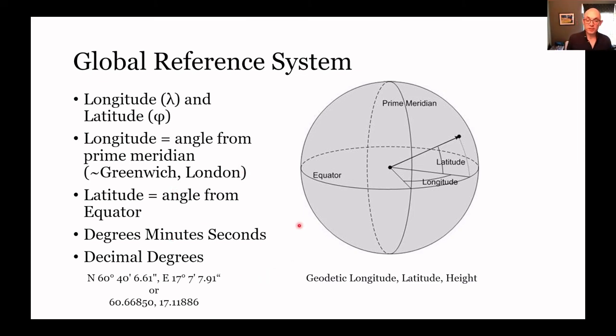And this coordinate system, as I said, defines everything in terms of angles. It's not a distance that you can walk along. It would change. We can illustrate this quite, hopefully you can see that this angle here, the longitude, as we move up closer and closer to the pole here, the same angle will cover a smaller and smaller part of the surface. So it's not very easy to work with.